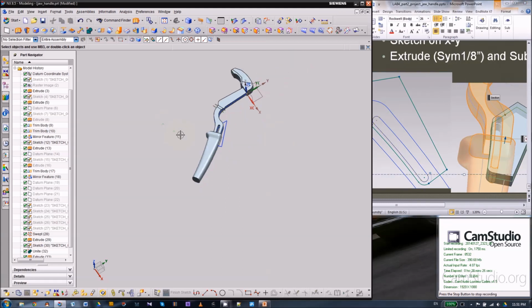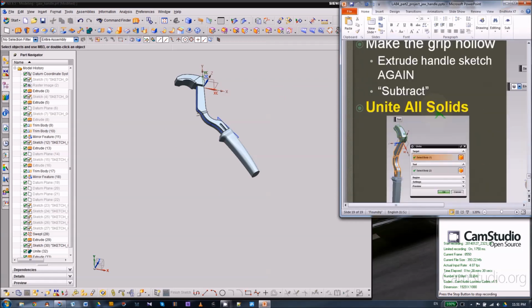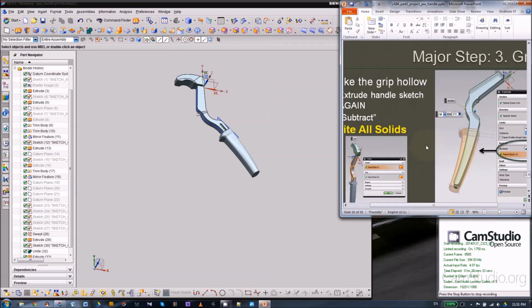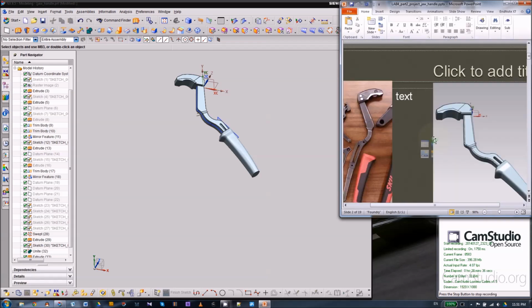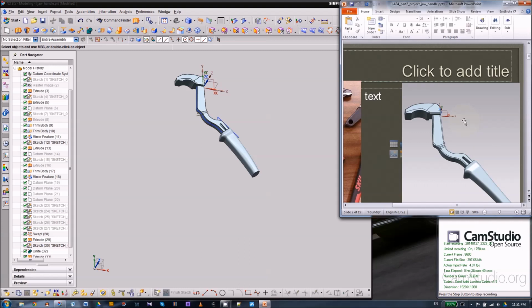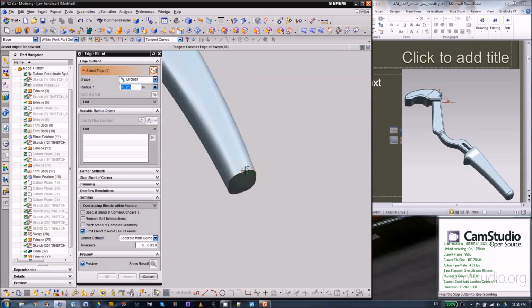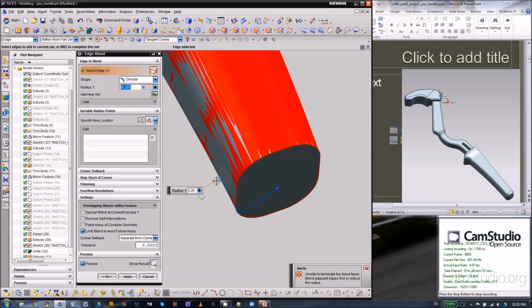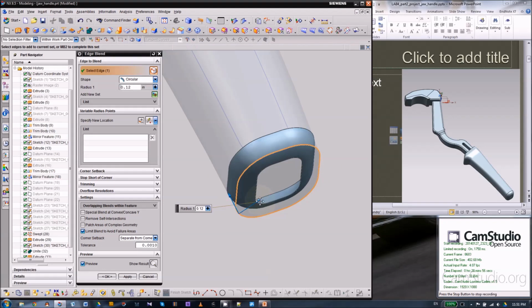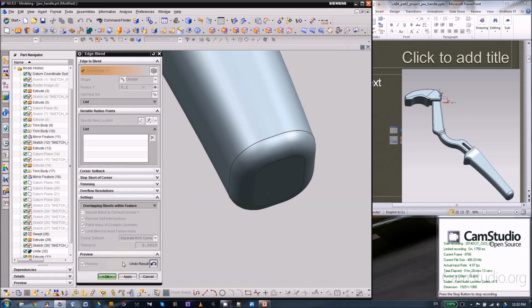If you like, and you can see in the slides, the first slide, I guess, we do have some chamfers and edge blends you can use to make the geometry look much better. Okay, so I'll just do an edge blend here, and this one's way too big. And as you can see, I have this setting expanded here. I think by default those two are clicked. If you have those two clicked, well, it's good now.